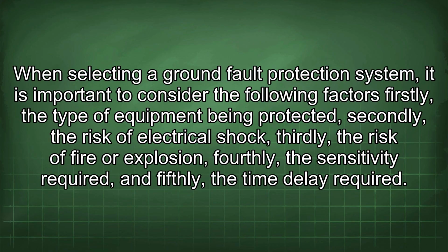When selecting a ground fault protection system, it is important to consider the following factors. Firstly, the type of equipment being protected. Secondly, the risk of electrical shock. Thirdly, the risk of fire or explosion. Fourthly, the sensitivity required. And fifthly, the time delay required.